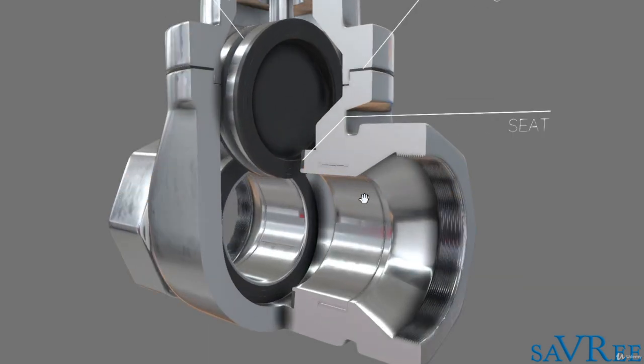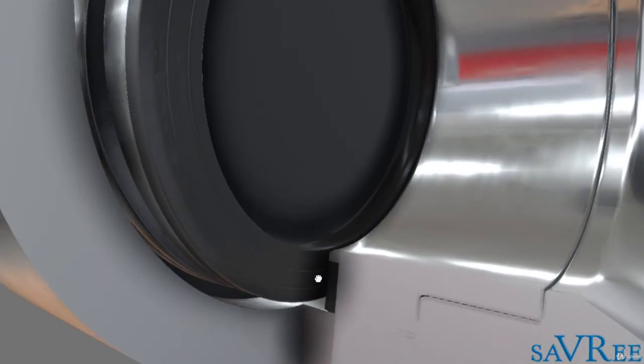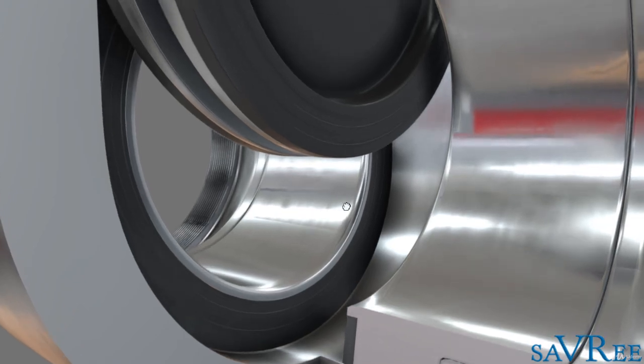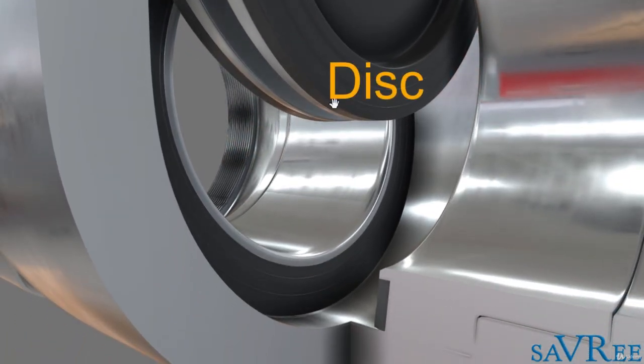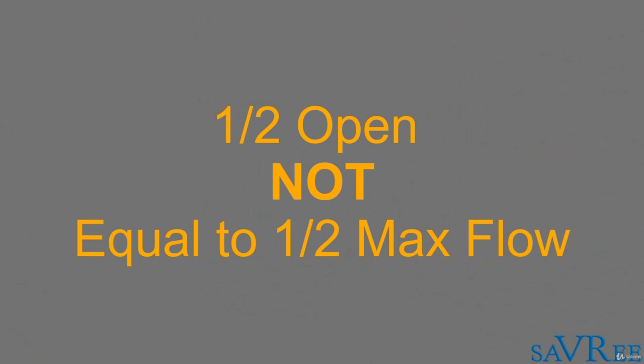I'll show you why. If we look down here at the bottom of the valve, you can see it's fully closed now. The disc is pressed against the seat. I'll pause it. Now it is only half open. So this is in the throttled position. The problem with this is that firstly, the amount of flow through the valve is not proportional to the amount that this gate has travelled. So the disc, this section here, has travelled up and it looks like approximately halfway. But the flow through the valve is not going to be half of the max flow capacity. The flow through the valve is not linear or proportional to the amount the valve is open.